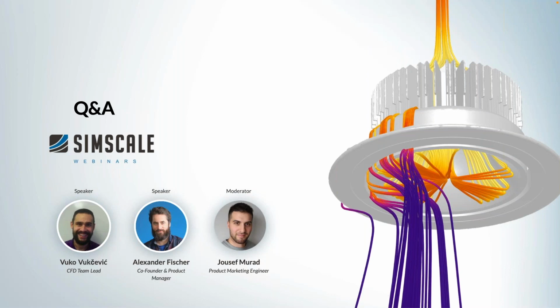So if your gap is smaller than the local cell size, then it will be closed up. Just to give you an example: if you have a gap of 1 millimeter and your local cell size in the area of the gap is, I don't know, 3 millimeters, then it will be considered closed.